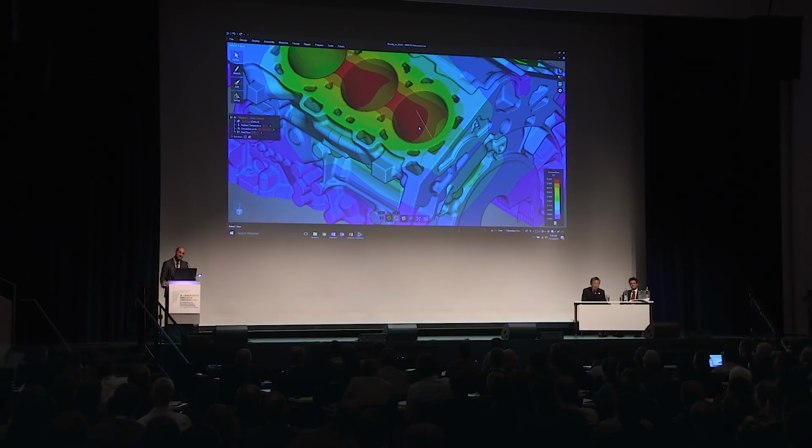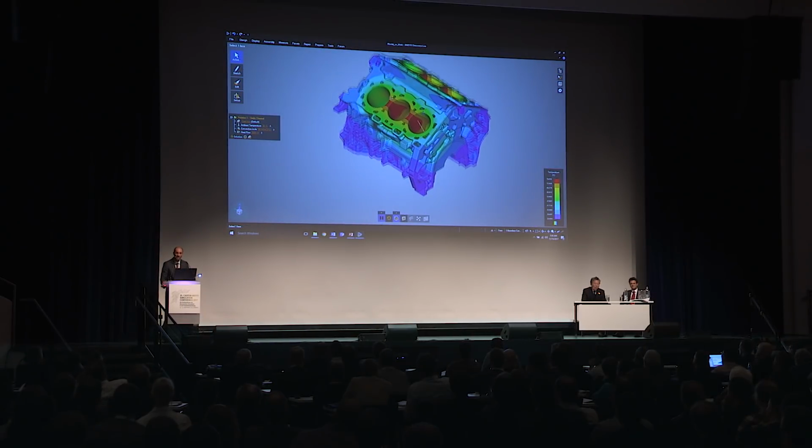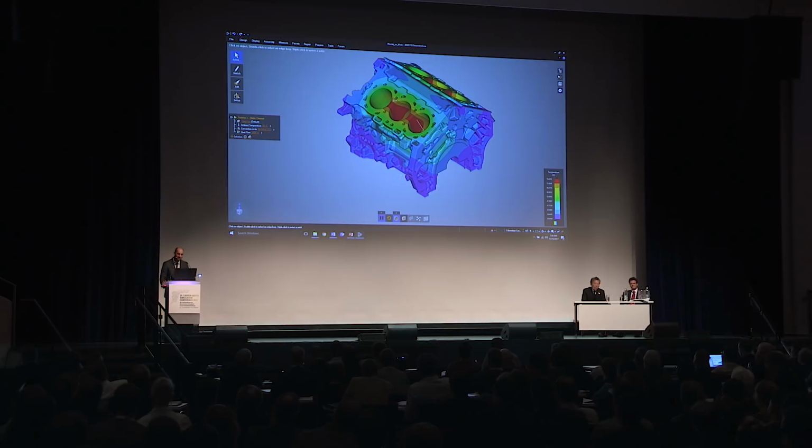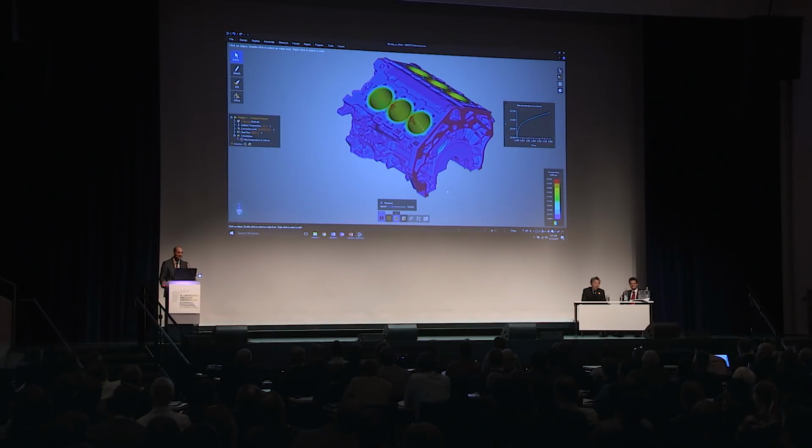Now, let's go one last final step further. So I put this engine block, right? And we can also do transient analysis. So we can look at not just how the heat ends up, but how it gets there. This is the kind of intuition that we want to be able to build with designers. We want them to understand the behavior part. We want them to be able to graph it. Let's say I want to add a calculator that's maybe the maximum temperature and the volume, right? So if I rerun this transient study, and believe me, it's resolving at each step, you can actually plot and see how long it takes to get to that final temperature.